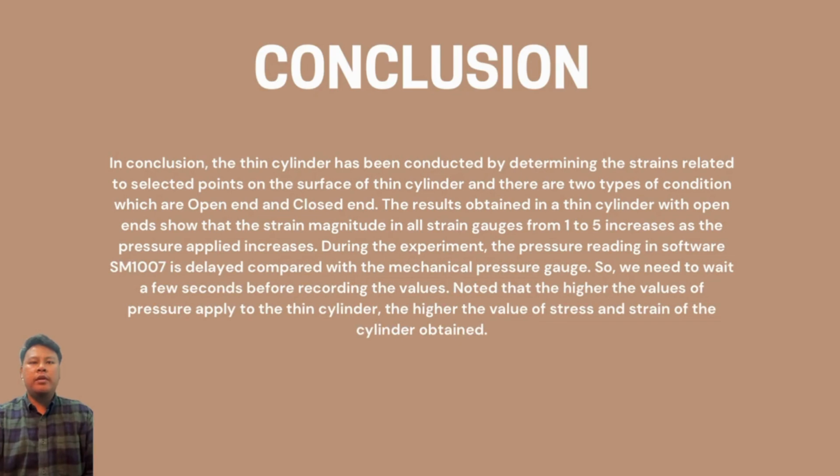During the experiment, the pressure reading in software SM107 is delayed compared with the mechanical pressure gauge. So we need to wait a few seconds before recording the values. Note that the higher the value of the pressure applied to the thin cylinder, the higher the value of stress and strain of the cylinder obtained.